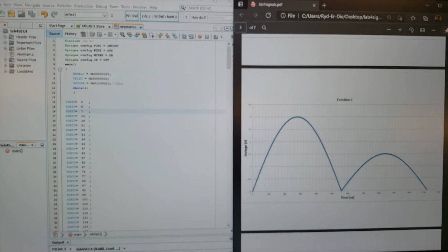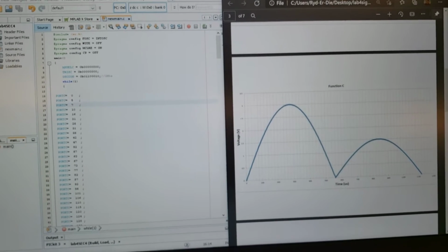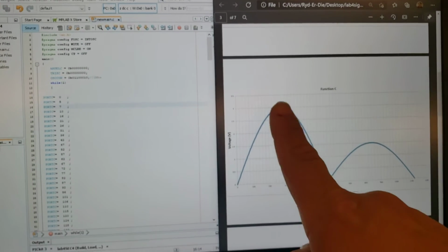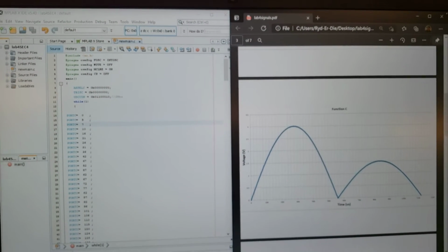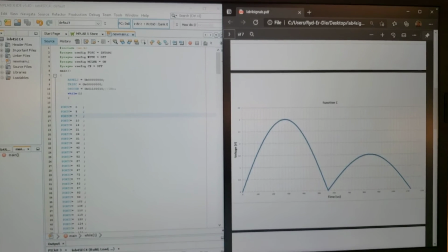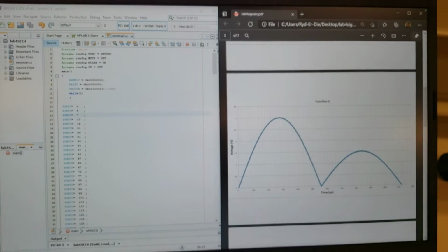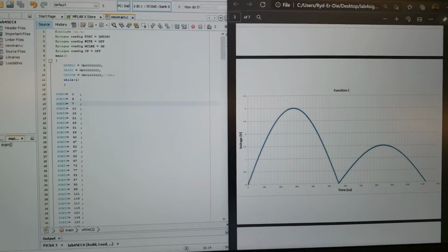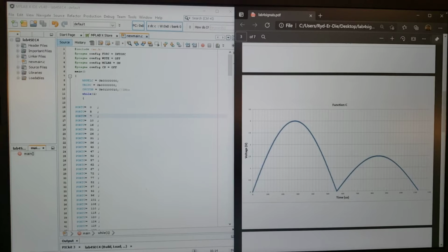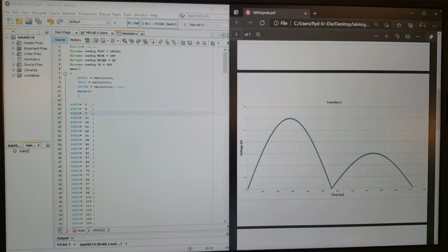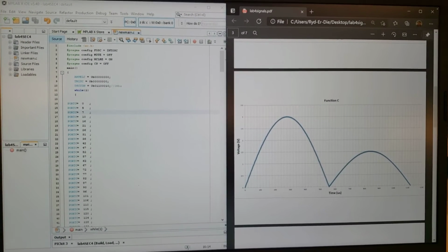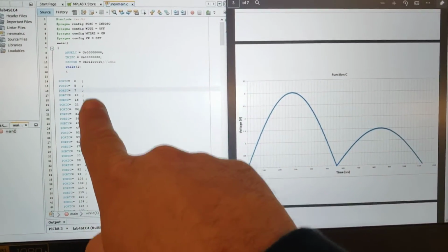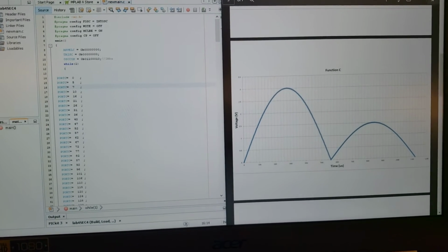We can always do it without it. This was just to save a little bit of time. We took 560 microseconds, divided that by 2 to give us our 90 degrees. Then we divided that 280 by 3.94 microseconds, which is the total command time, to give us a total number of points required for the 90 degrees each of 71.06, rounding down to 71 commands, which is all of our port commands. We have 71 total here.